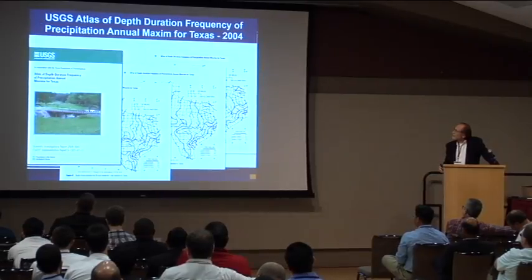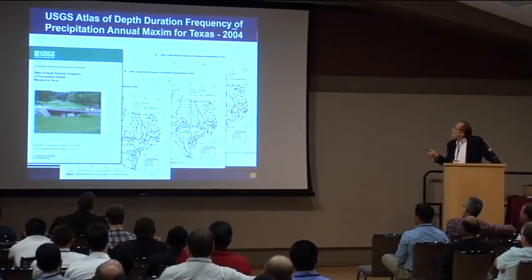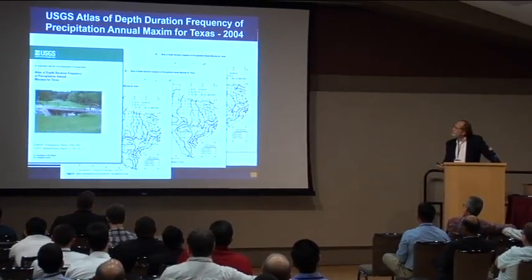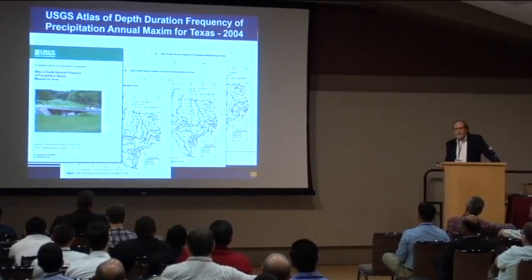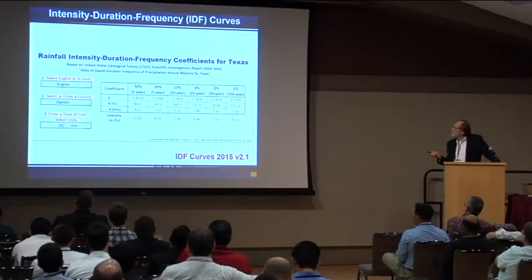The new IDF curves are based off of depth, duration, frequency by USGS. One thing I might want to point out is that report was generated in 2004. So the data sets in that report are probably 3 or 4 years old, so that means your IDF curves are roughly 15 to 16 years old. So in our case, this is just a temporary until that NOAA 14 comes online.